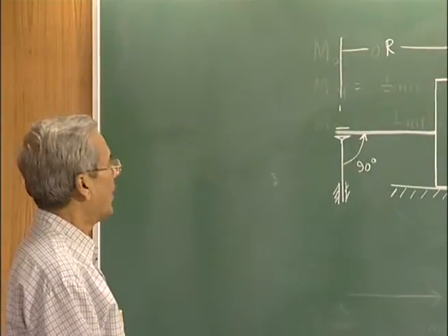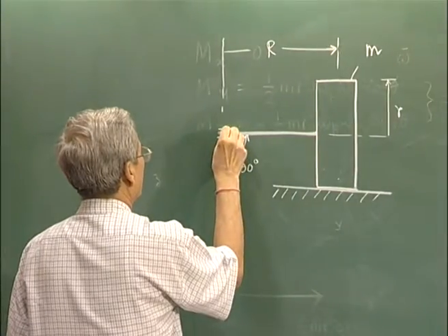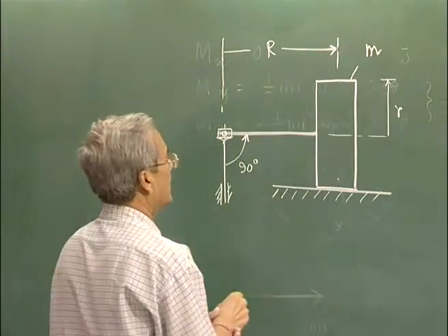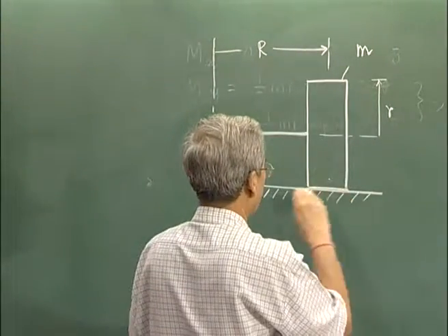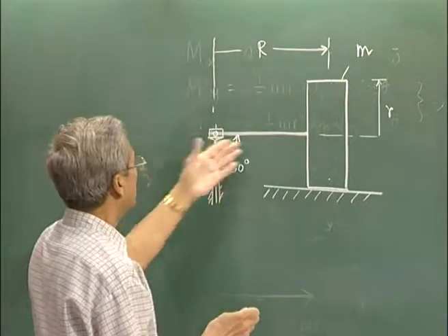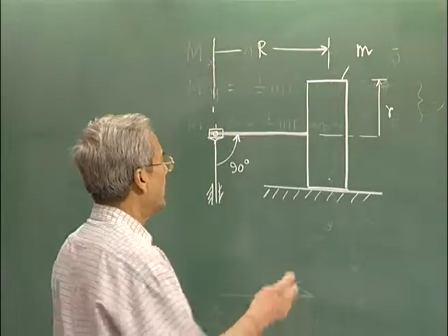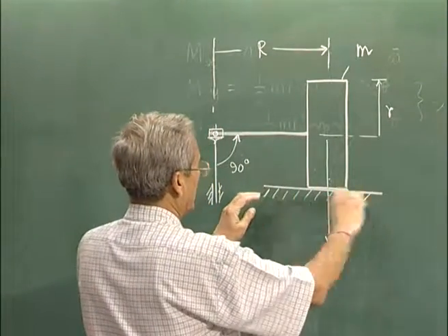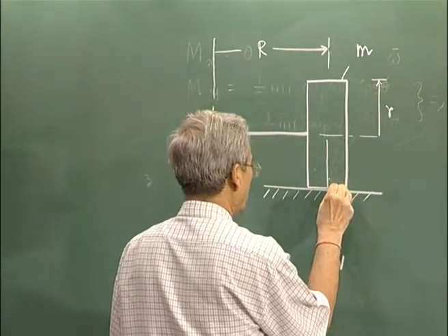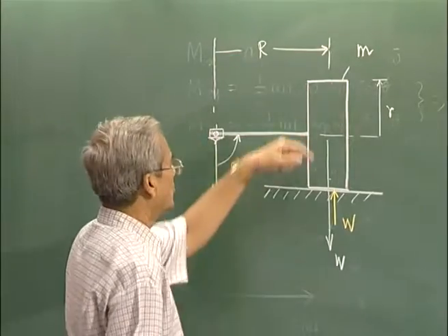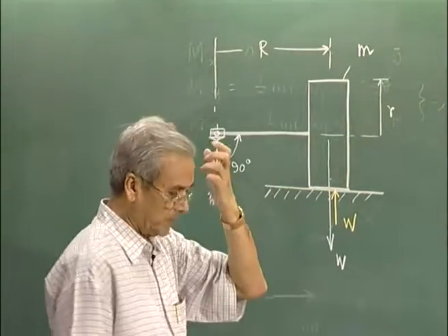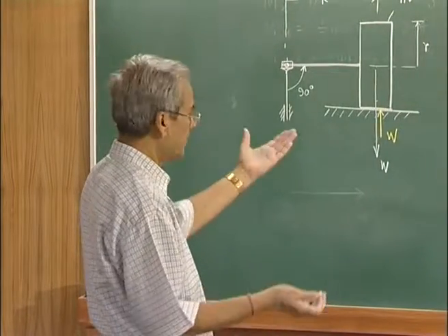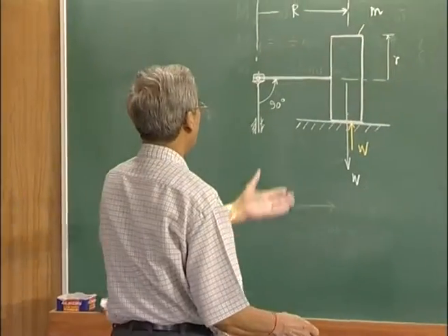So what we expect, and this is hinged here, is that the total force acting here will be simply the weight of this, if we ignore the weight of the arms, etc. So if the weight of the disc is W, then the reaction between the floor of the crusher and the crushing roller will be simply W. So this weight will be just balanced by this, and the crushing force will be W. So if we call it a 10-ton crusher, it means that the roller has a 10-ton weight and it can produce a total crushing force at the contact point below of W.